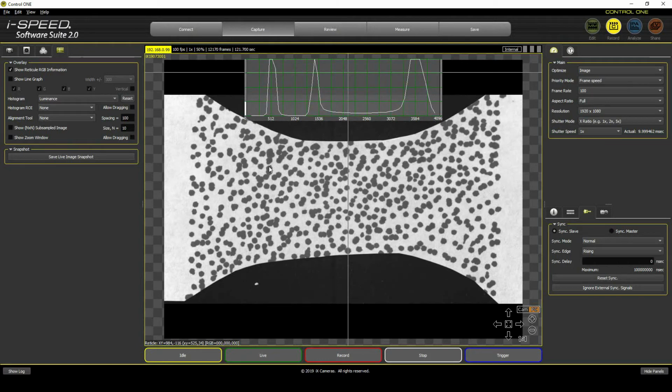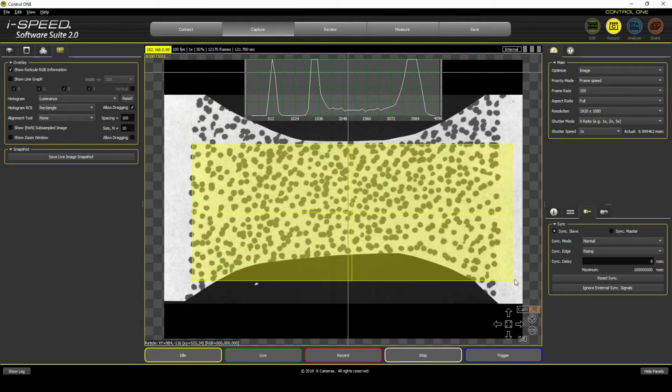And so again, this is another accurate method of making sure we have not got saturation and we've got great ability to do correlation on this image. If you want to be a little bit more accurate, you could say, well, I don't really care about the luminance histogram in this area. I want to actually have a region of interest, so I can create a rectangle, bring it in, and just histogram this area here.